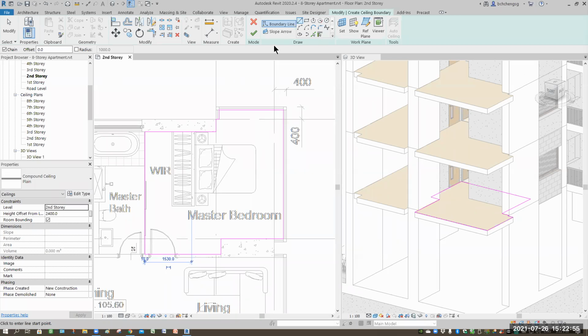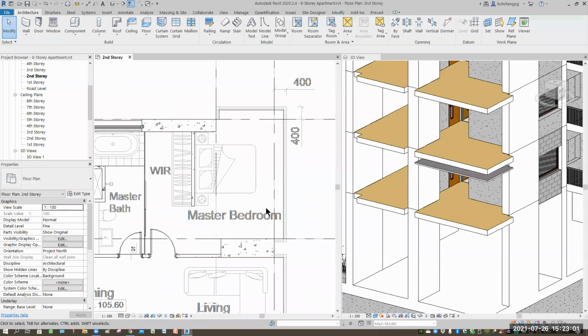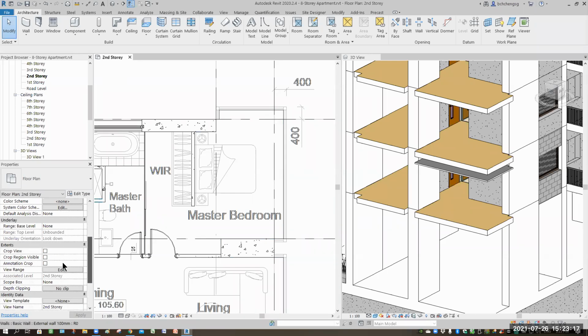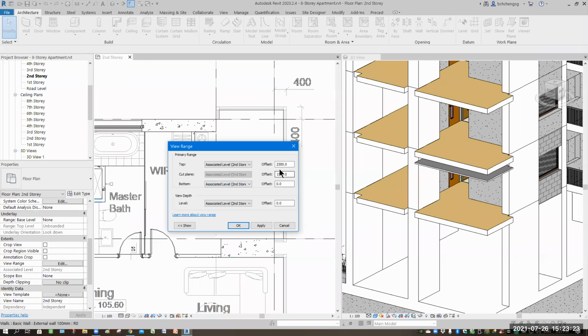Okay, now if I click OK, you see that by right it should warn me, but it doesn't. I don't know what happened to my Revit 2020. Because you are drawing something that the view range doesn't permit. If you go in closer, you notice that the view range is at 1.2, maximum 2.3.